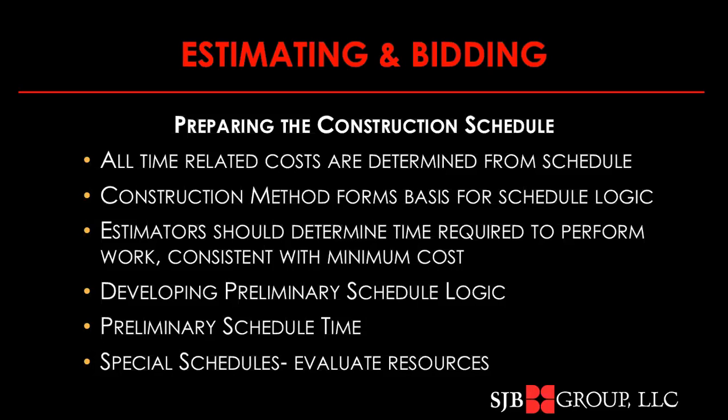You need to consider the procurement of key items, especially your long lead time items. You need to allow time for the inspection and testing of various parts of the work. You need to allow time for the submittals and shop drawings. There may be an assembly period, a mobilization period. Sometimes there's certain preparatory work that's allowed to be done during the mobilization period.